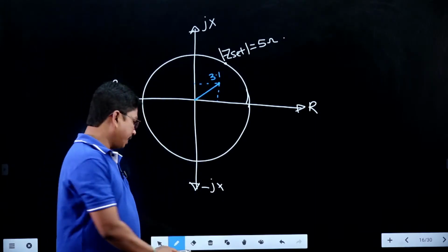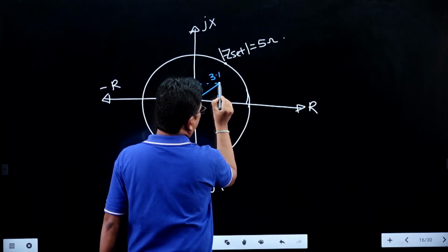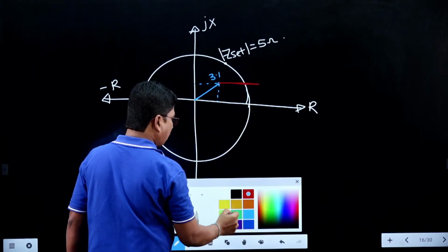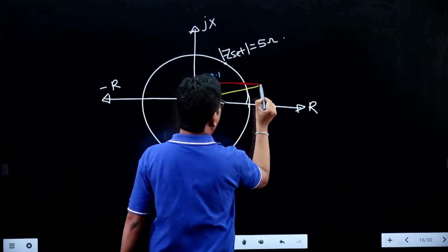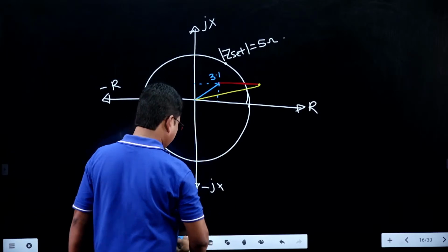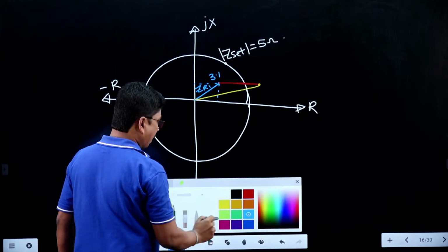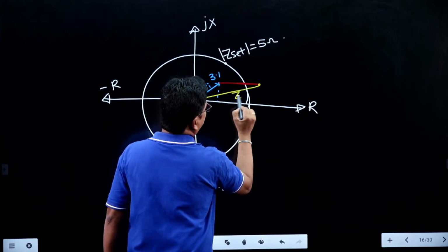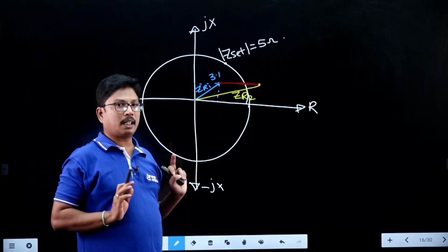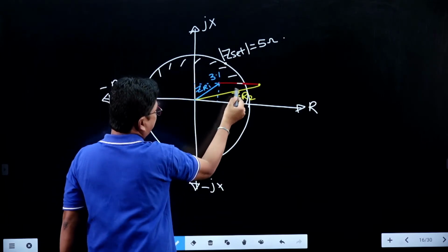Now because of arcing faults, some arc resistance is added. That arc resistance, this is the resistance, is added here. So the overall relay looking impedance is this one now. So this is the relay looking impedance now, right? Previously this was ZR1 initially, and now we have ZR2. As ZR2 is increased and it is more than Z set, the relay is going to operate only within this zone.